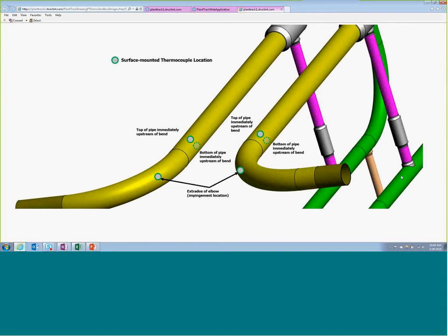So this is a bypass line. Again, it doesn't mirror the actual application, but this is just for demonstration purposes. So you see here that we have this bypass valve, my pressure reducing valve, and you come along here. Well, the nearest thermal well is actually located way downstream. So you really care about areas here where you potentially have pooling or impingement.